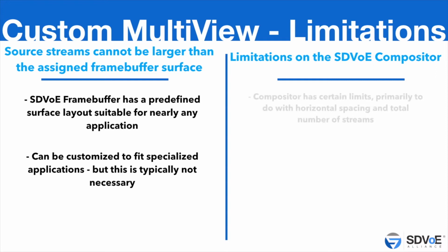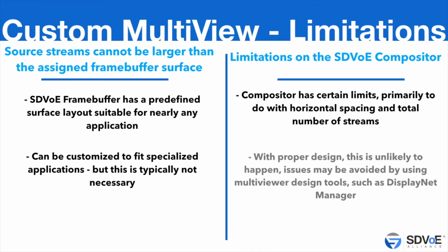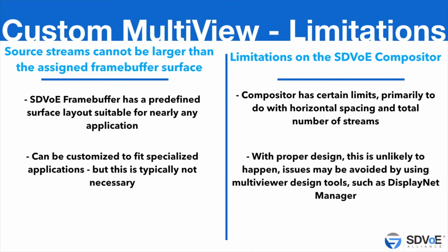There are also several limitations on the SDVoE compositor, primarily to do with horizontal spacing. There are certain limits as to the increments as to where you can place windows, and the total number of streams on the screen. With proper design, this is unlikely to happen, and there are certain design tools that we happen to provide, such as DisplayNet Manager, that can help you mitigate this.